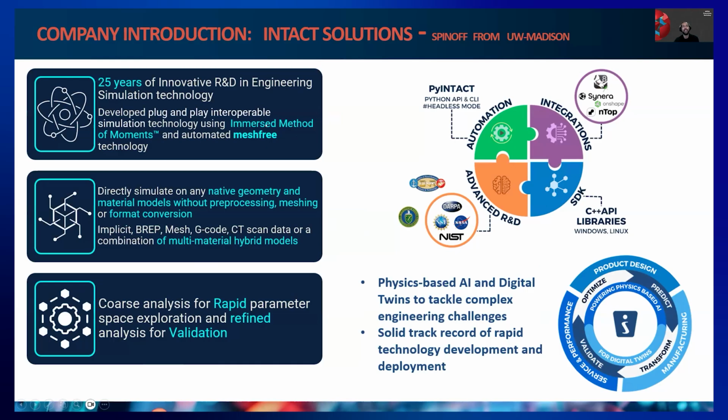So here we have an immersed method of moments technology, which is essentially a mesh-free technology. What it means is users can simulate directly on native geometry and material models without any pre-processing, meshing, or any format conversion. That's the whole idea. What it means is users can bring in different kinds of geometry, implicits, B-reps, meshes, G-codes, CT scan data, voxel data, and they can mix and match all these different geometries to set up simulations.